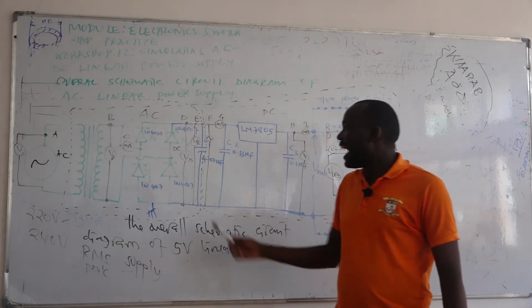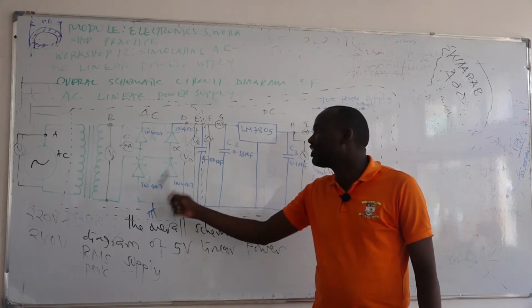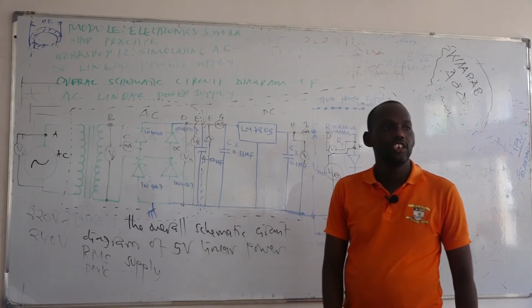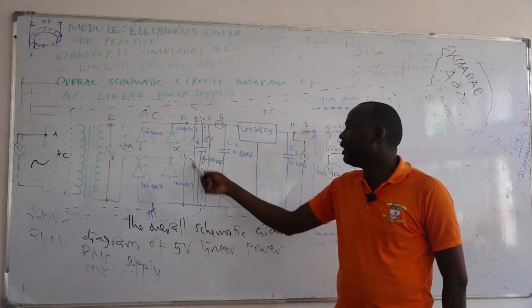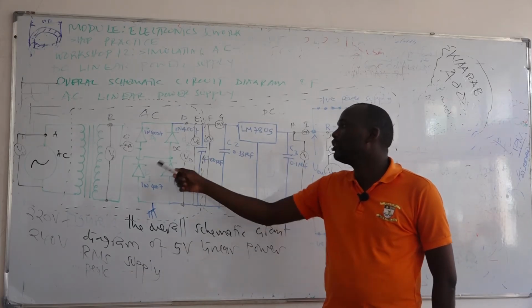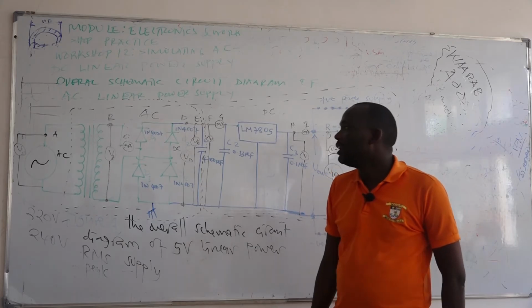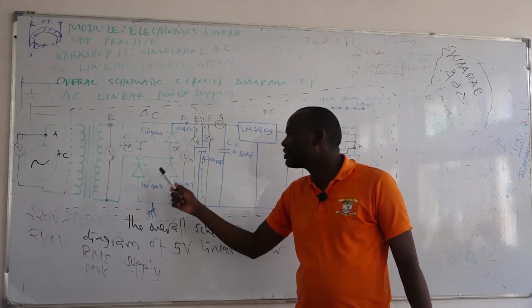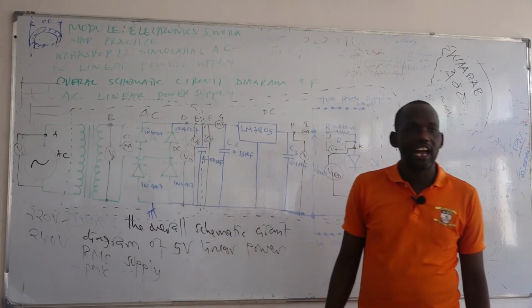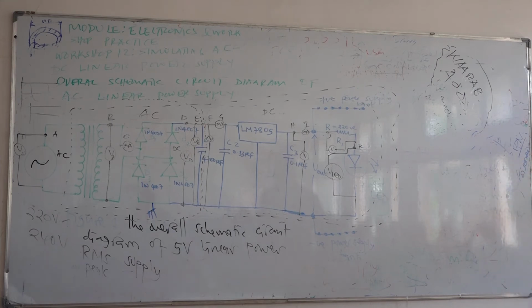The answer is very simple if you refer to what I told you. Listen. There's no need for you to measure voltage across diode 1, diode 3, diode 2, diode 4. Why? These two voltmeters will measure what is actually dropping across these diodes. Remember that the 4 diodes that we've used to build a rectifier are not conducting current at the same time.